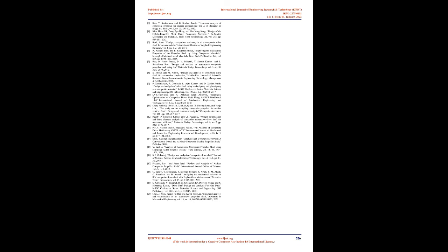8. Conclusion. In this study, a comparison of steel and composite drive shafts. Its design technique is investigated, and certain critical parameters are found using finite element analysis. The current effort intended to reduce the fuel consumption of vehicles in particular, or any machine that uses a drive shaft in general. The developed shafts fulfill the design standards for shaft design. Steel shafts and composite shafts are developed to suit the design criteria. The theoretical shaft design values are virtually identical to the analytical shaft design values obtained using an analysis tool, Ansys.